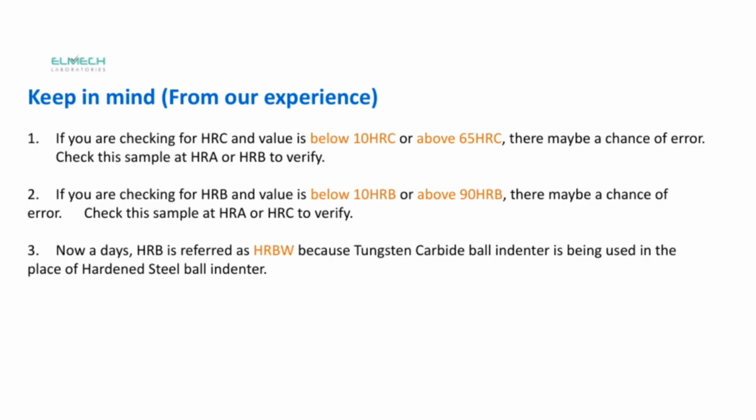Secondly, if you're checking for HRB and the value falls below 10 HRB or exceeds 90 HRB, again, there's a possibility of measurement error. In this case, it's best to check that sample at HRA or HRC to double-check your results. Finally, a quick note on terminology.